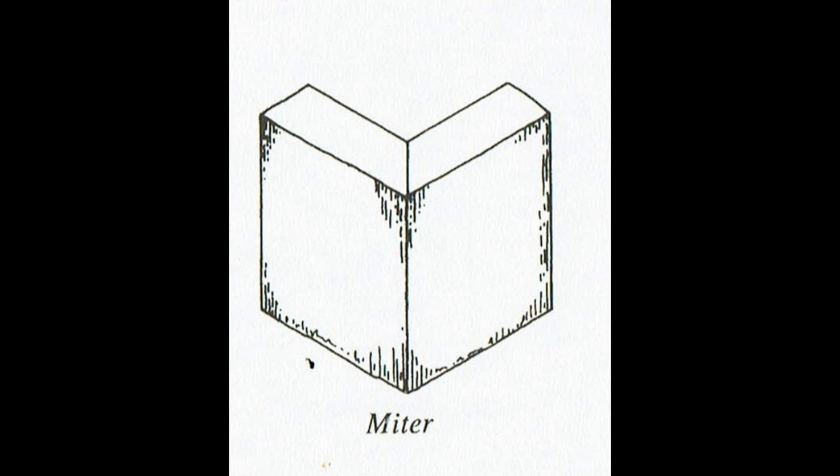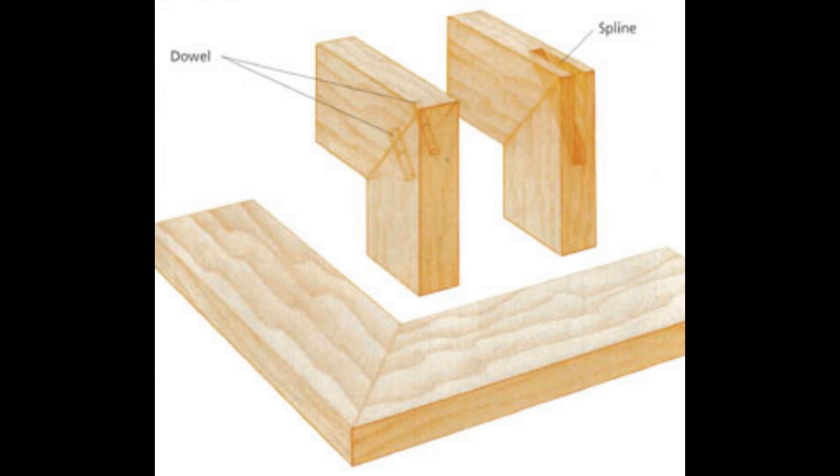How to attach these depends on what you have available and what the finished product is supposed to look like. Most commonly used is having the joint done and then using some sort of wide crown stapler or corrugated fastener to attach on one side only, because you'll want the other side looking pretty nice as the finished product, to ensure that everything is held together.